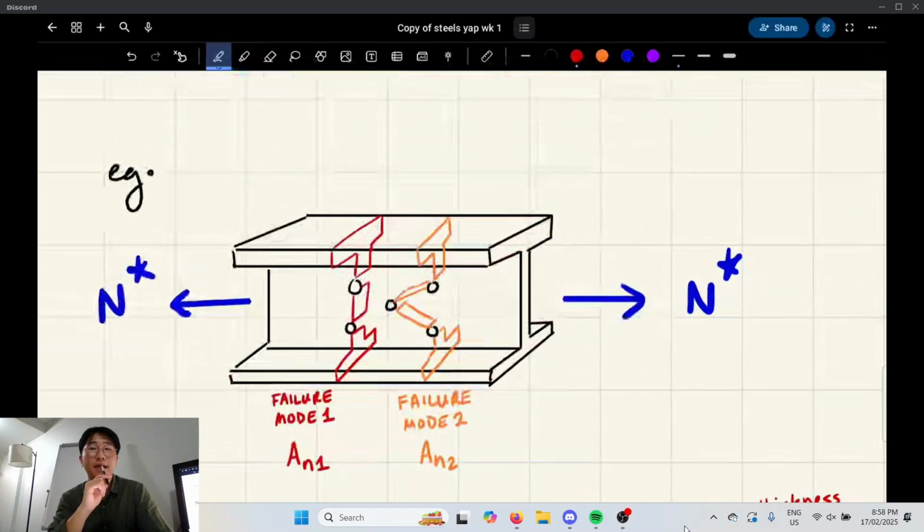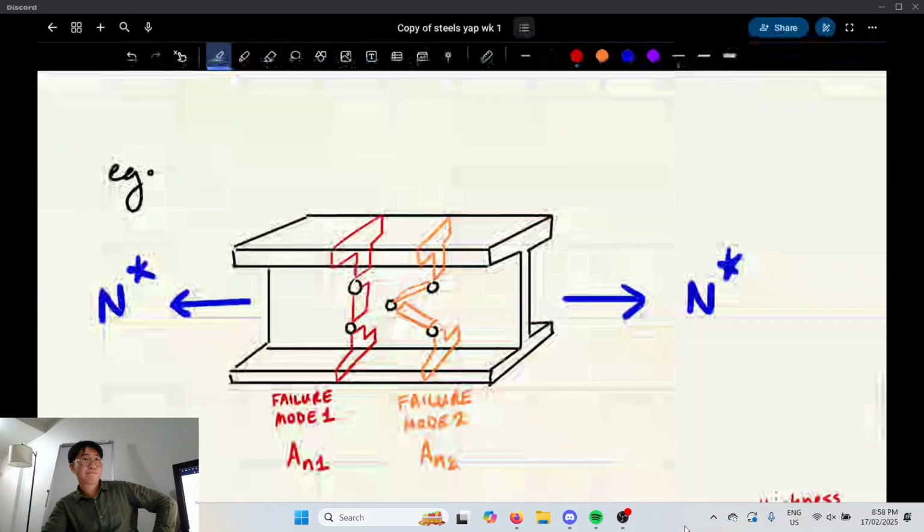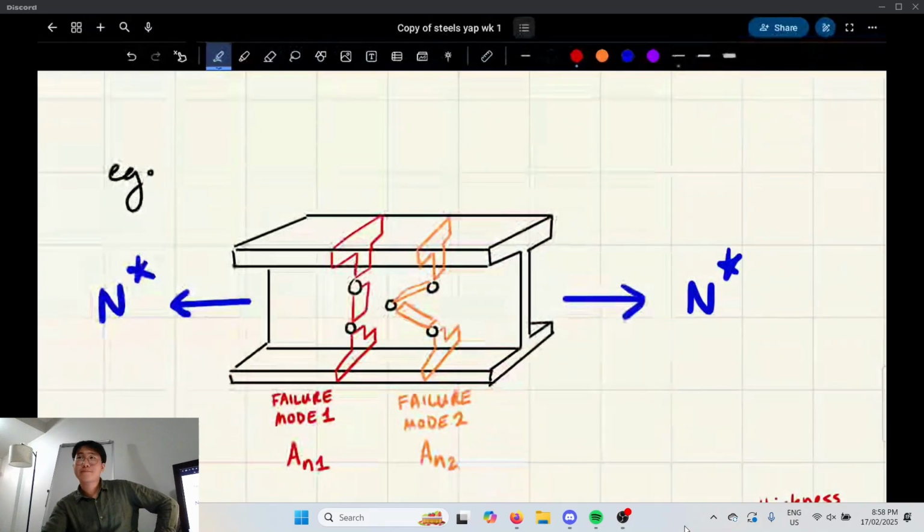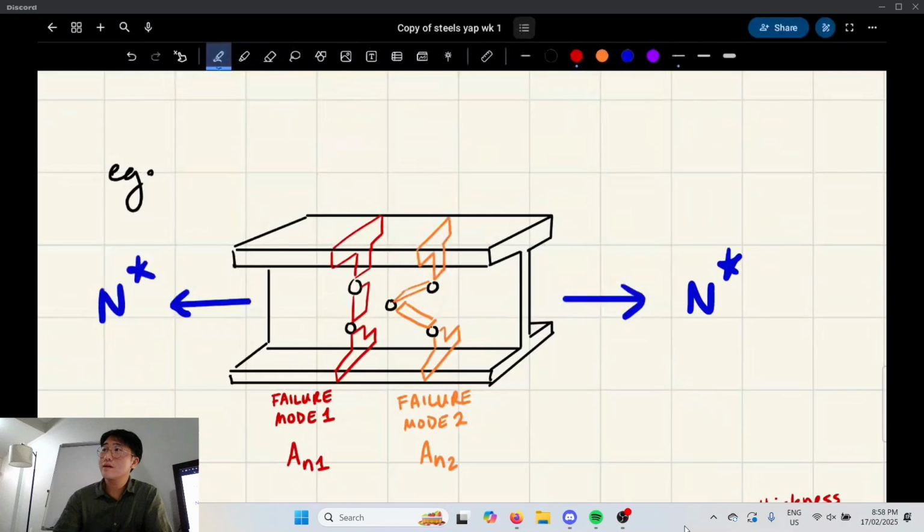One of them is breaking more towards the center. Firstly, what are these holes from? No, what are these holes from? It's from the tension. But they didn't just spawn out of nowhere. There was a reason. They were drilled through. Yeah, the bolts. Right. And so bolts will reduce the cross-sectional area, making it weaker, right? But then if you're stretching it, it has to travel a longer way. Yes. So I'll talk about that in a sec.